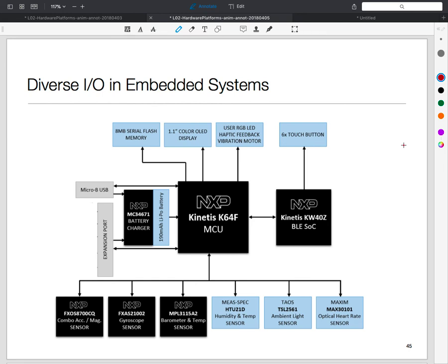Sometimes they will have a barometer also on it, and because a barometer gives you absolute pressure, it gives you altitude above sea level, so then they call it 10 DOF. But whatever useful thing you are deriving is different. When I say that to fully characterize a rigid body, I need 6 DOF, then you can derive those 6 DOF and track this over time.